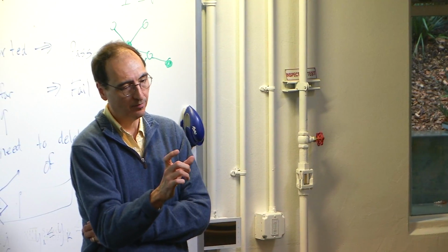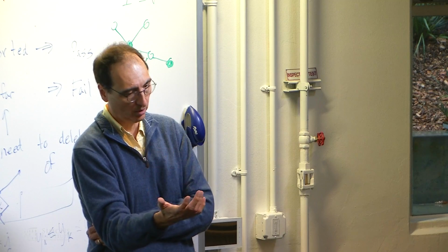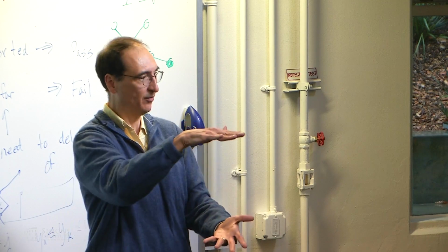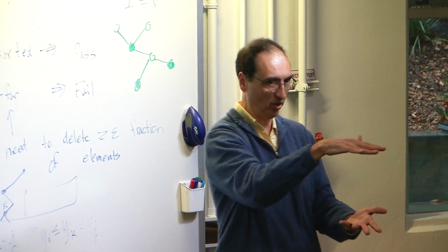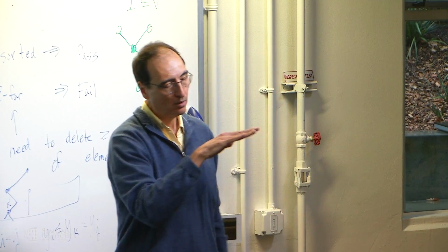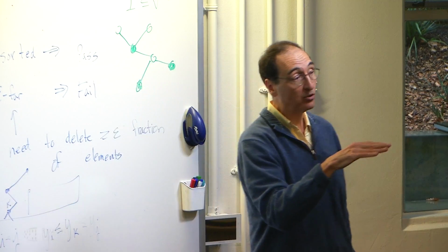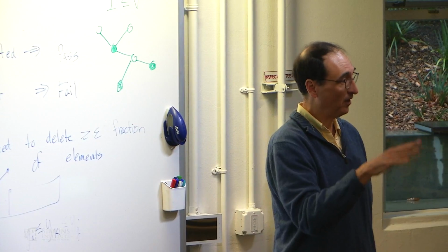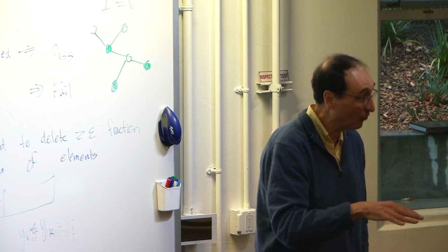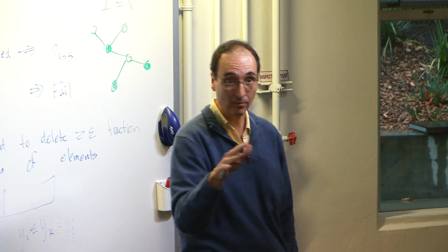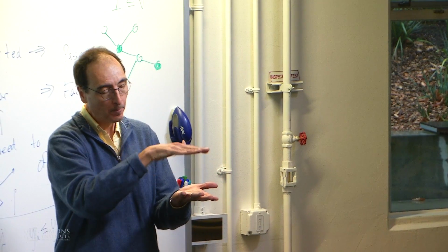One of the things that makes quadrotors work is that, more or less, you say hover and it just hovers and holds. They're really good controllers. So why does that work? Well, it works because they have pretty accurate gyros and accelerometers. That's a technology your cell phone is driving, because they're getting better and better, like the ShakeAlert stuff, et cetera.